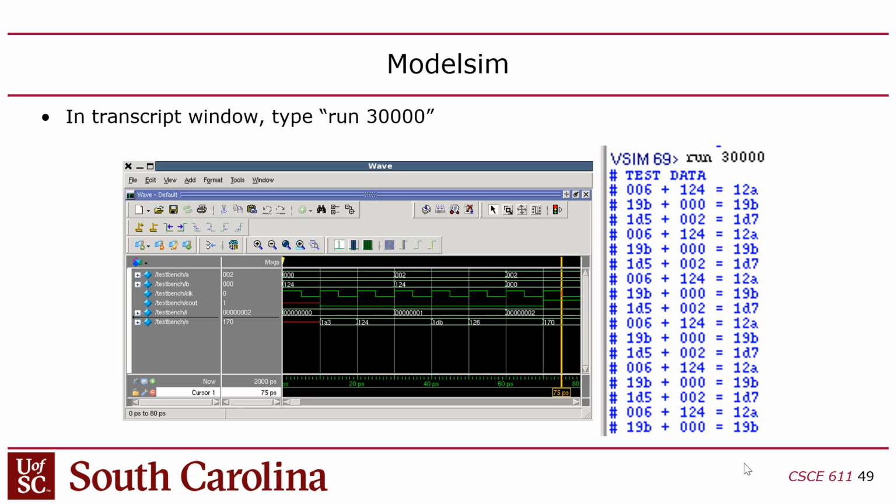One thing I want to mention here, though, is that QuestaSim uses the Tcl language as a scripting tool. So you can do things through the GUI, and then you'll see the corresponding Tcl command. And then you may find that you just want to write commands in the command window, or you can write a script, because there's really only a few commands you need to know.